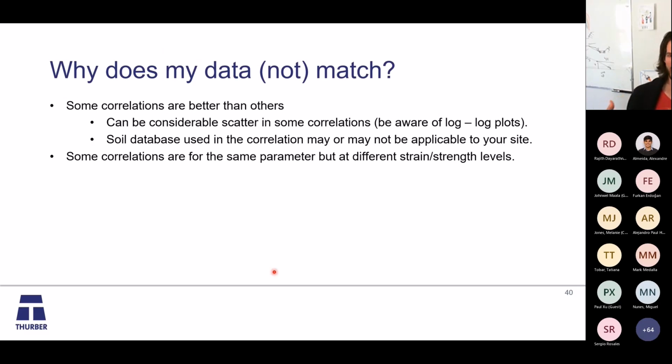And we always have to ask ourselves, why does my data match or not match? And some correlations are better than others, and there's considerable scatter in the correlations. So like I said, be aware of these log-log plots. And the soil database used in the correlation may or may not be applicable to your site. And then some correlations are for the same parameter, but they're at a completely different strain or strength level to your application.